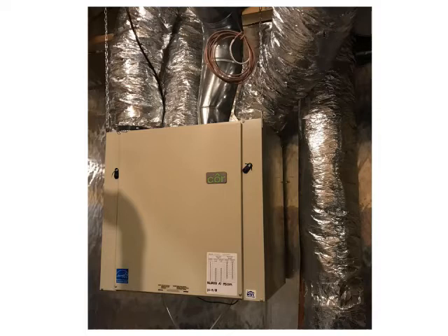The difference is the HRV is just the heat. So the air that's going out, through the heat exchanger, the core, will condition the air that's coming in. Many of these are 60–70% efficient, so it's really a good thing to ventilate the house with. An ERV, an energy recovery ventilator, has a latent component. In other words, the air that's going out has a tendency to dry the air that's coming in. So instead of having to dehumidify that air again, it's actually drying it out slightly.